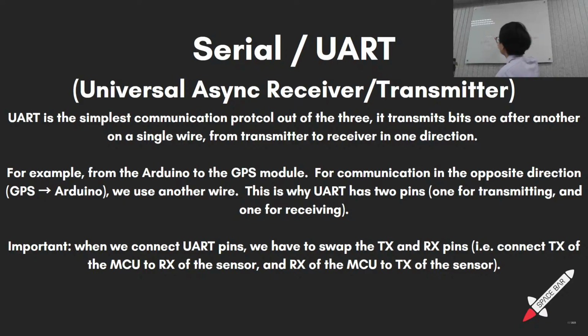Okay, anyways, with UART, there are actually parameters which we have to set on both the host and the device. We have to set the baud rate, which is basically how many symbols it sends per second. Using the baud rate, you can figure out how long a UART data frame is.